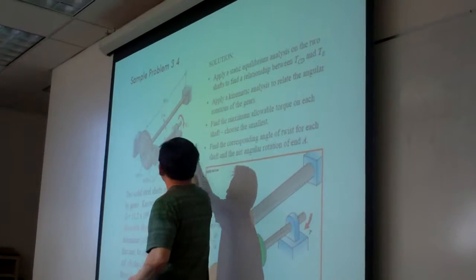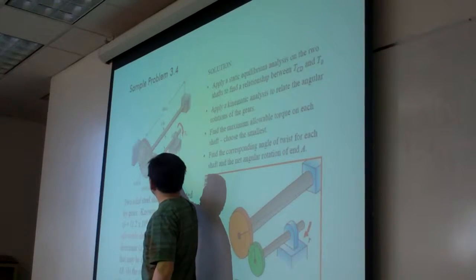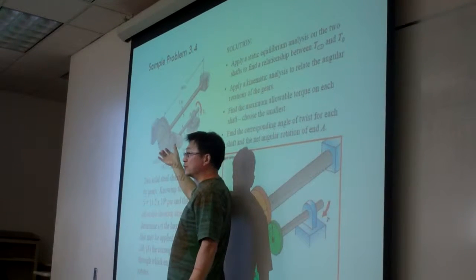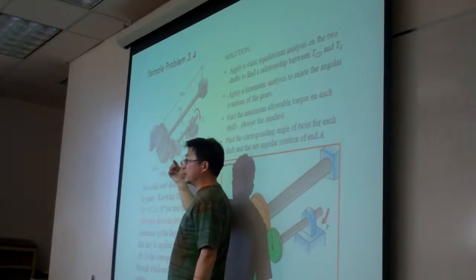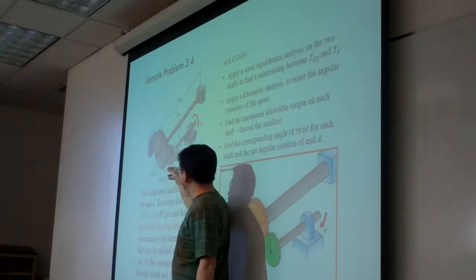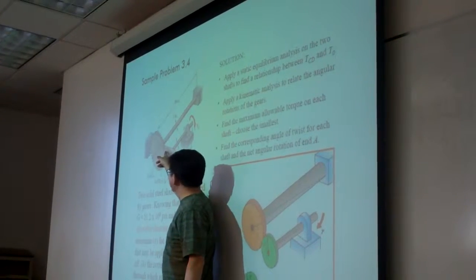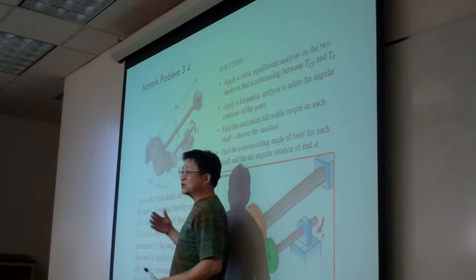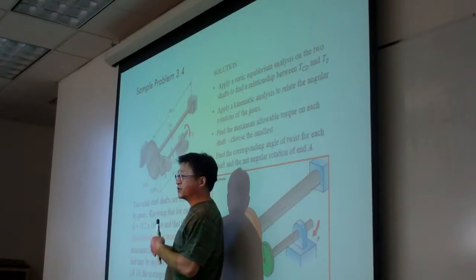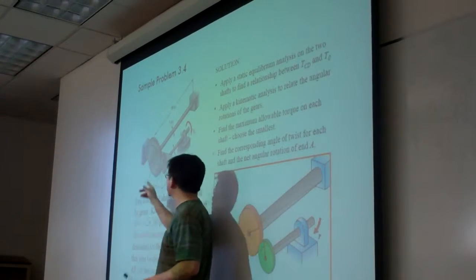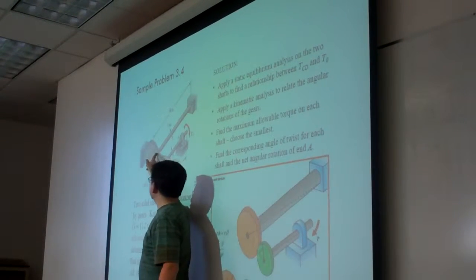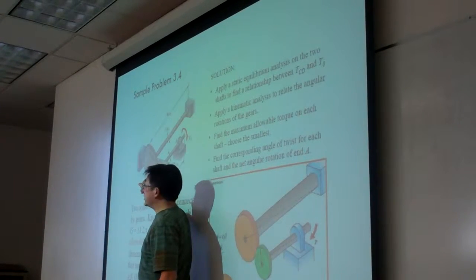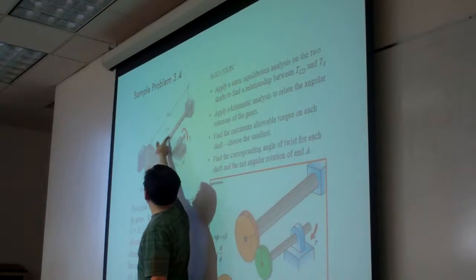The torque is applied here, trying to twist this shaft. The shaft is elastic, so it will be twisted a little bit, exhibiting a twist angle. Then the torque is transmitted to gear B, and gear B, as a rigid body, transmits the torque to D, to C. Because C is welded to the shaft here, the small rotation of C will drive this shaft to twist.